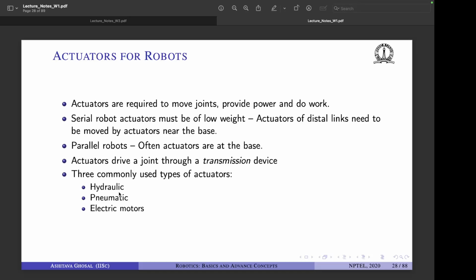In pneumatic actuation systems as well, you have to have a system for controlling the pressure of the compressed air and pushing that air to those joints, right? And there are issues of leaks and loss of pressure. But electric motors are quite clean in that sense. They can be neatly compacted into devices which have an additional gearbox in front of them.